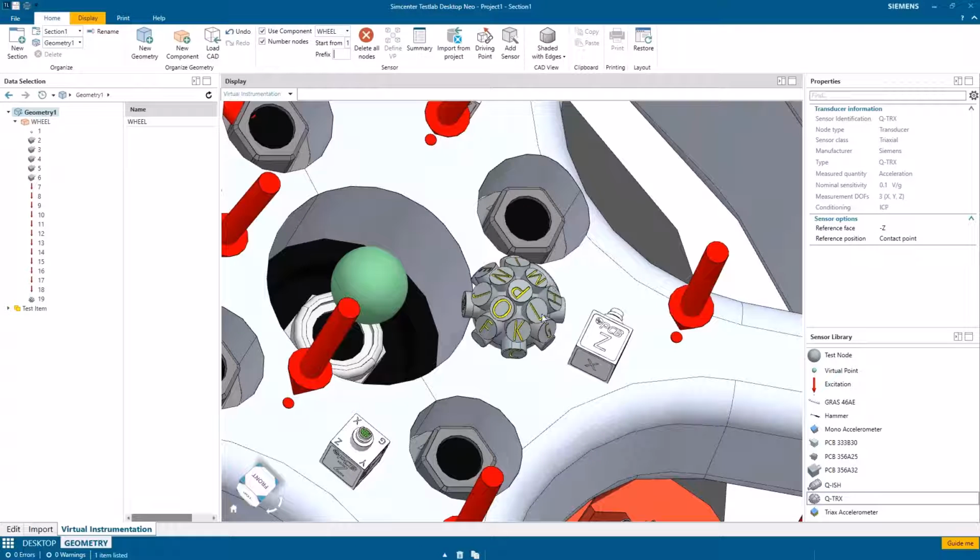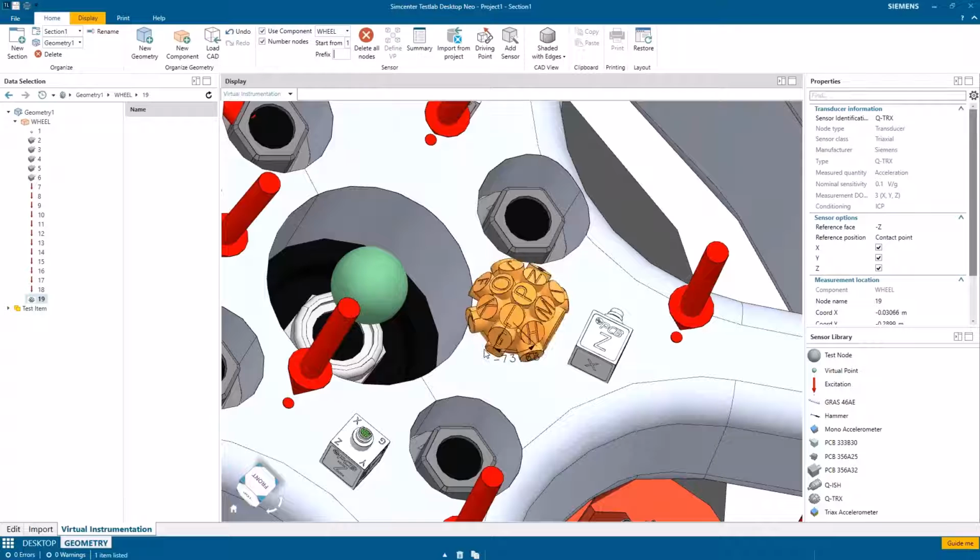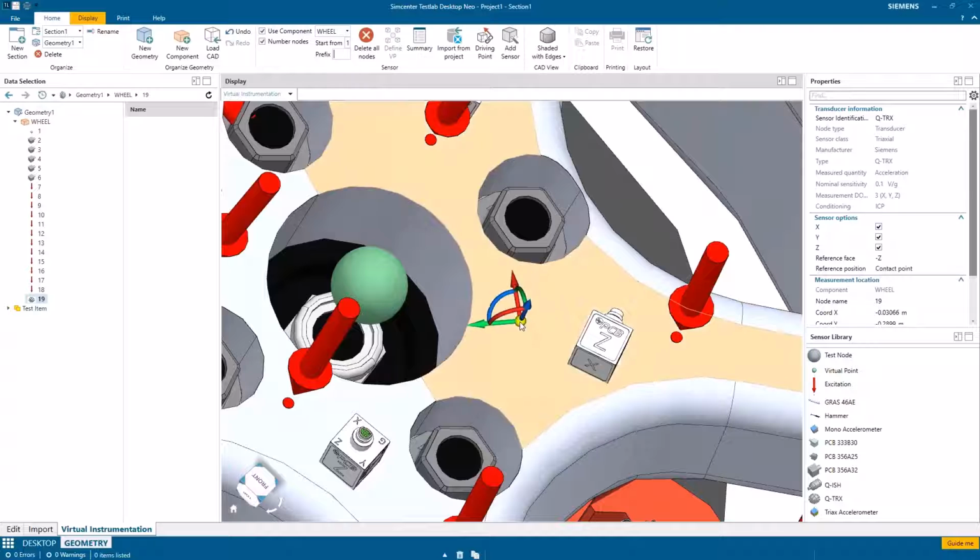And these angles are associated with these letter indices. And so if I take measurements at the L and the F faces, those angles and orientations are already baked into Simcenter Test Lab, and so it will automatically extract those angles for me, provided I've oriented the QTRX itself in some way that is reproducible.